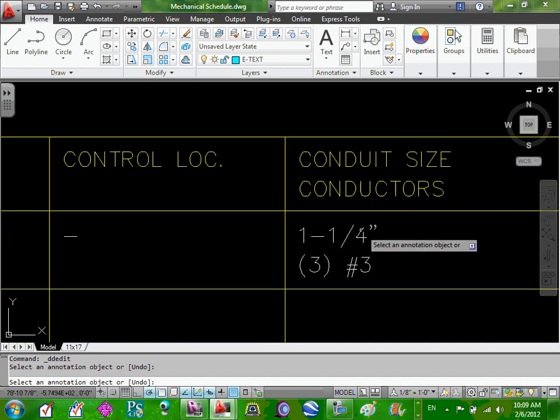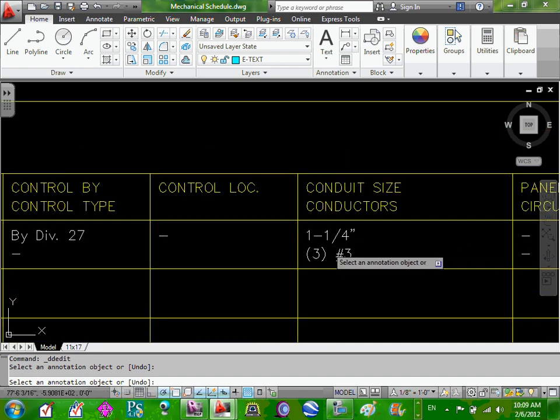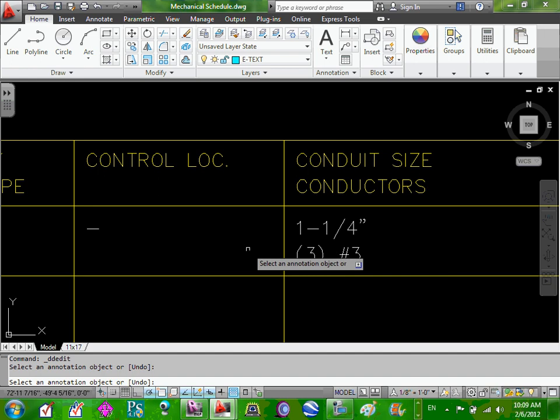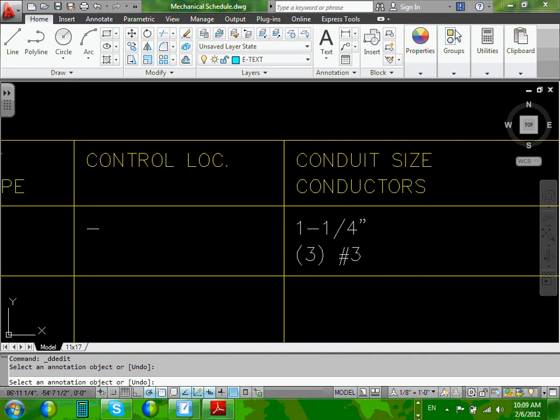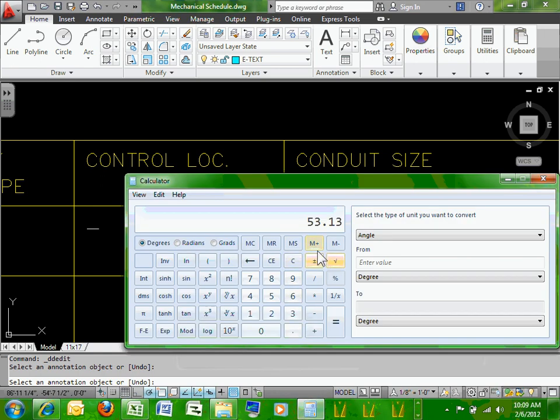Okay, conduit size. Now for conduits, you're going to size conductors. We talked about this when you size the equipment, and I'm going to go very quick here. You have 1.25 multiplied by the motor current, 46.2. This is how you're going to size the cable.